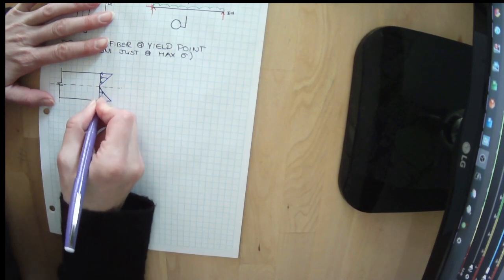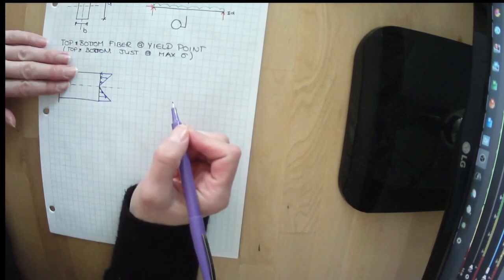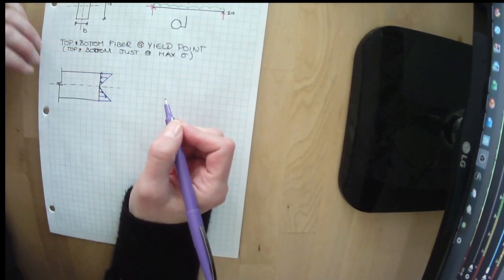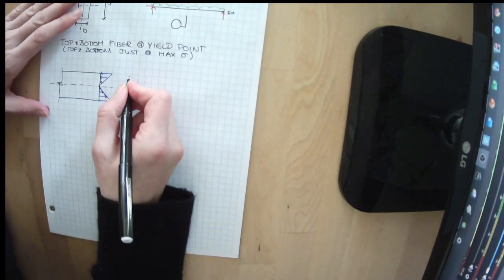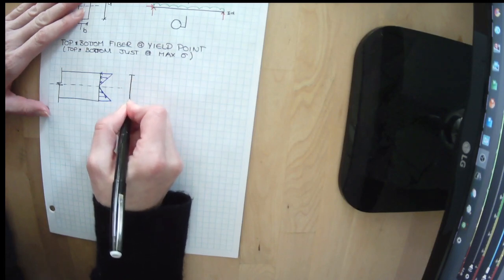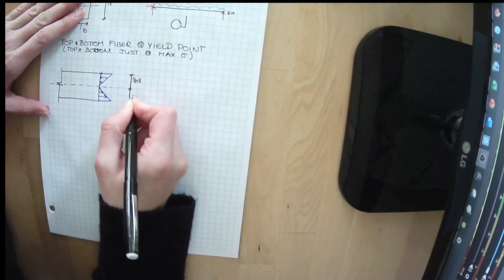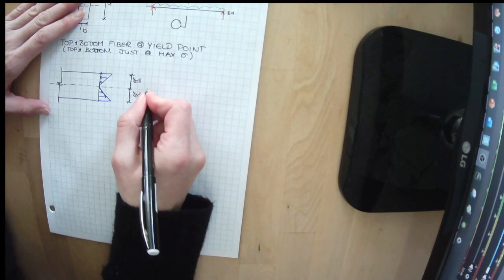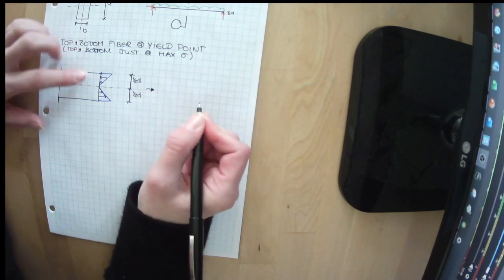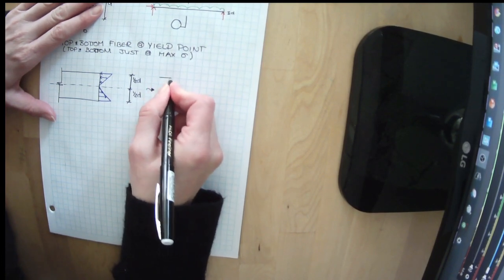If you guys remember, this was the same thing as it being drawn on a diagonal, but we just shifted this side over, so it was a little bit easier to look at. And remember that this was the entire depth D, so we could rewrite this as 1/2 D and 1/2 D. Well, drawing this as a stress can be a bit of a pain, so let's draw it instead as the force through its centroid.